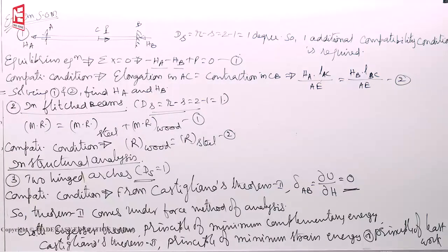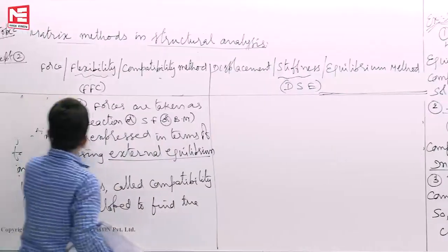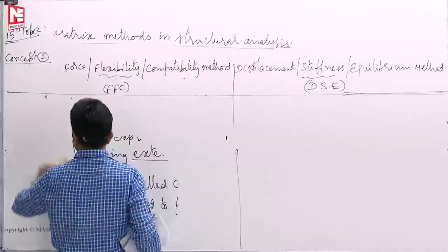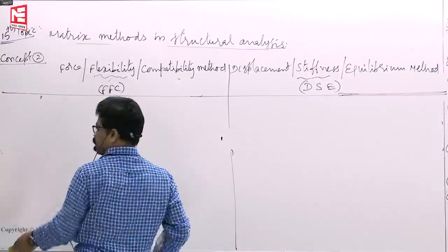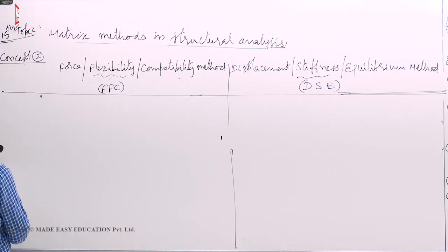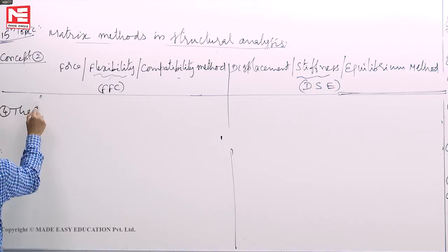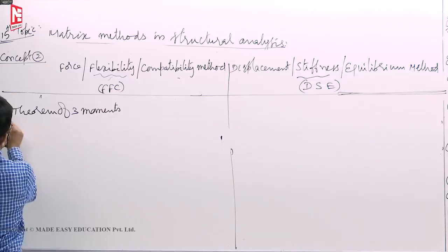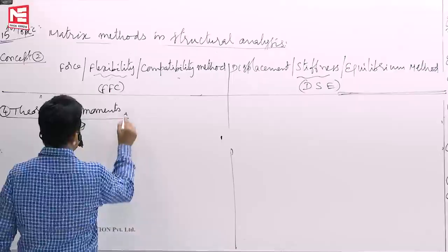Next, another method we have studied, 1, 2, 3. The fourth one I am writing here because already it's full. Another force method that we have studied is the theorem of three moments. Here also you will take the compatibility condition developed by Clapeyron.